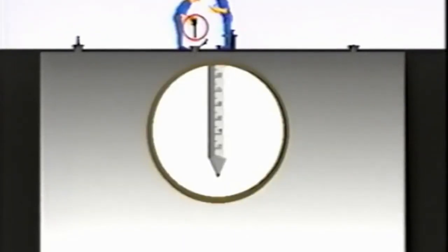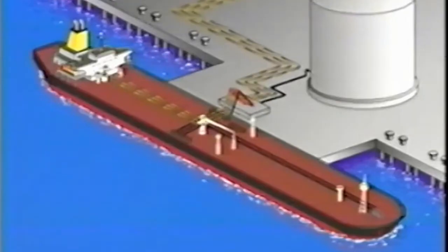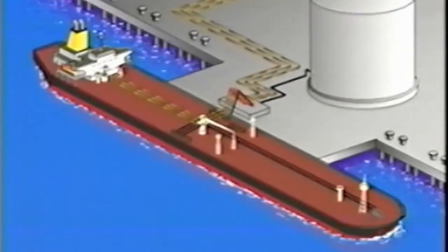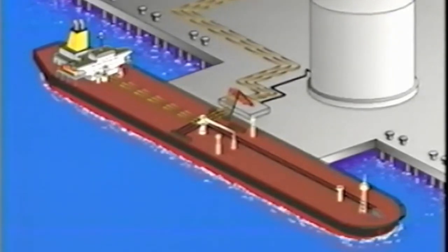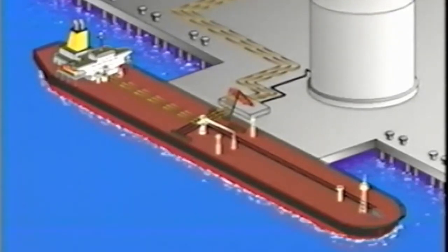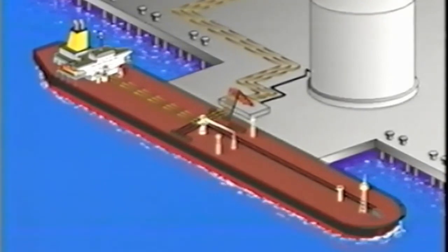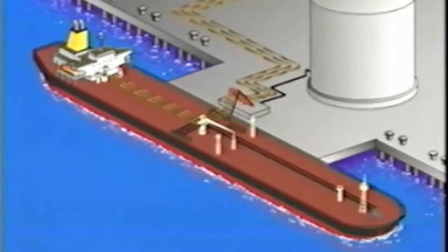Measuring cargo should be done by an experienced officer. Great care should be taken to record results, times and methods used. These are valuable facts to use in any dispute on cargo quantities. The volumes given by the ullage tables are seldom exact. When you load the vessel, you will, most of the time, experience differences between your own figures and shore figures. Your problem is to take on board a full cargo without overloading nor short-loading the vessel.